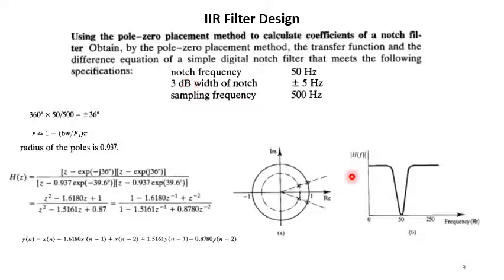So based on the figure shown here, you can see that this is the notch filter. And why is this a notch filter? Because you see it stops just this part of the frequencies. For all other frequencies it has a response that is non-zero, right? Or roughly we can say that this is basically equal to 1. So the response is 1 for all the frequencies except those frequencies that are around 50 hertz.